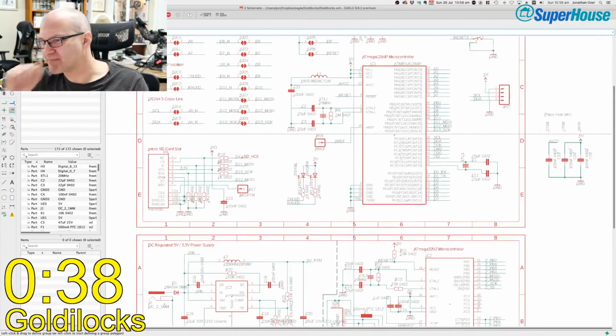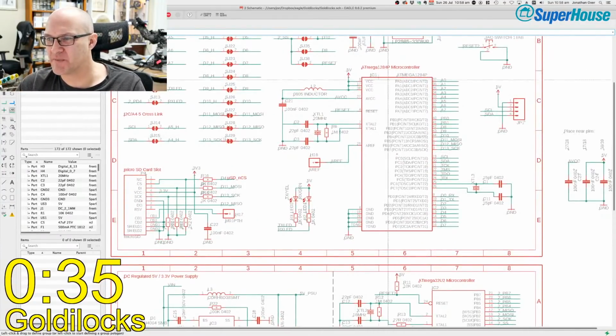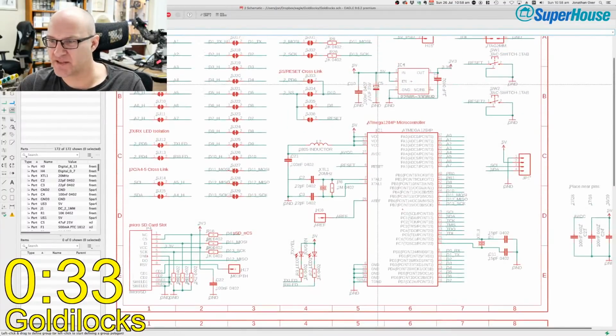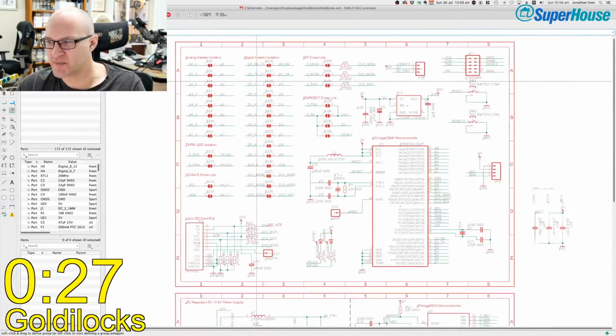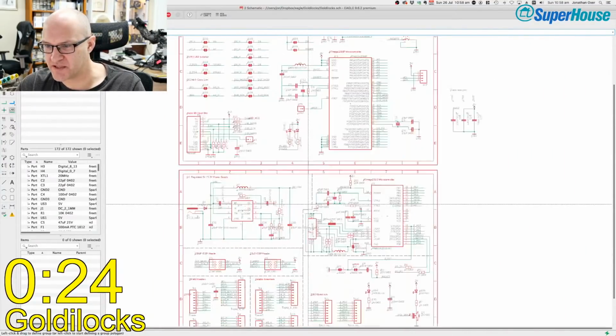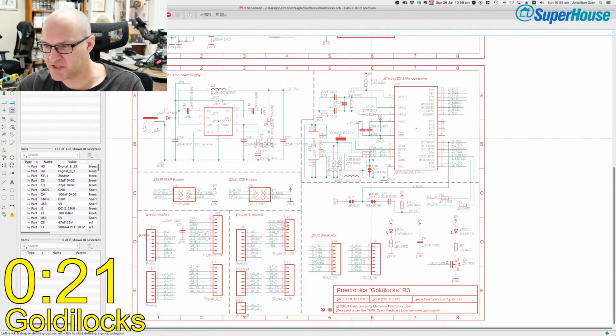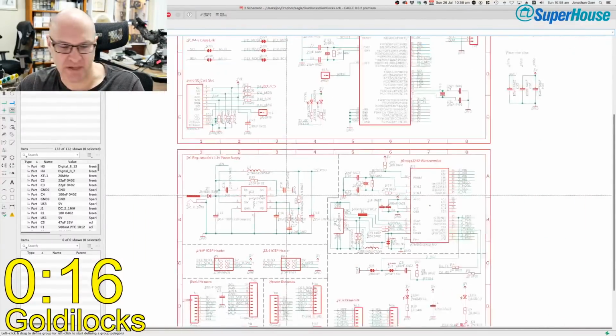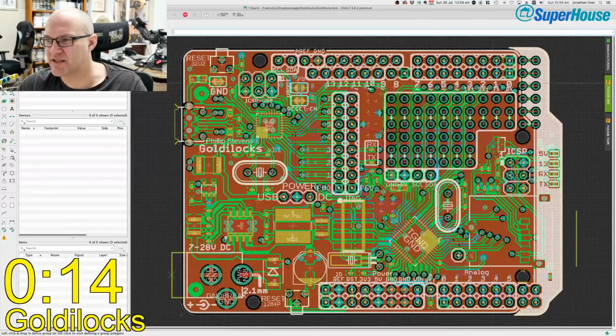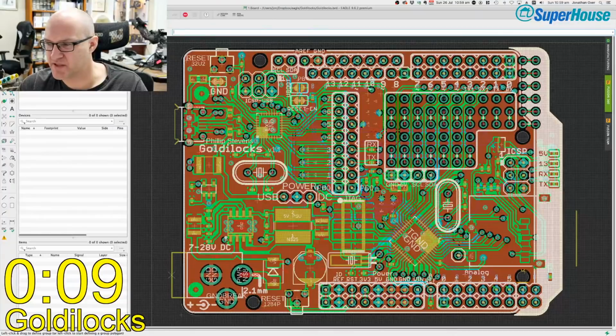So this is an Arduino compatible board with an ATmega 1284P on it. So once again, lots of RAM, lots of flash. It's got everything configurable. You can see all the cut track jumpers here so that you can isolate different parts of the I/O. It's got ATmega 32U2 with all of its I/O broken out, and it's got a switch mode power supply. So this is like a super Uno. It does everything. It's the everything in the kitchen sink sort of board. And you can see that it's a little bit longer than a regular Uno. This white part on the end is the extended section because it's got extra headers that wouldn't fit.